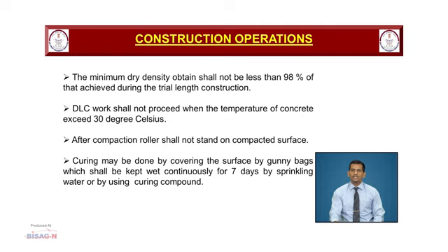After compaction, the roller shall not stand on the compacted surface. Curing may be done by covering the surface with gunny bags, which shall be kept wet continuously for 7 days by sprinkling water, or by using curing compound.